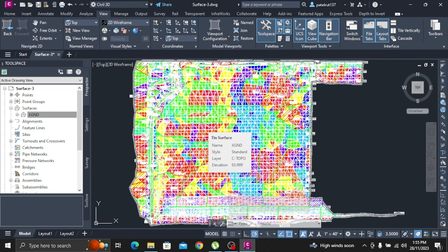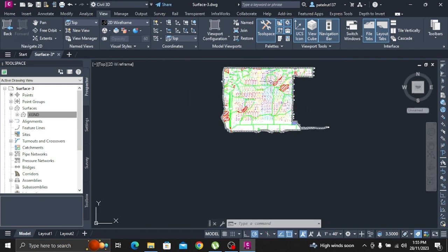This method of surface labeling is useful when you want to lay out the path of surface contour labels before you create the labels. If you wanted to create the path and labels simultaneously without first drawing a polyline, you would click Annotate tab, Labels and Tables panel, Add Labels menu, Surface, Contour - Multiple, then draw the path.